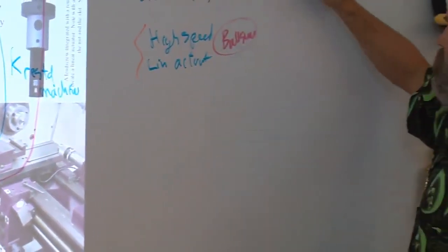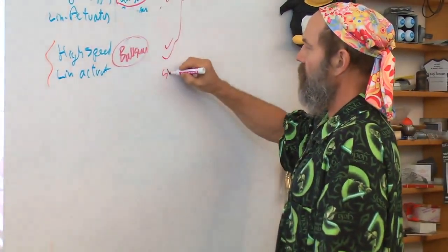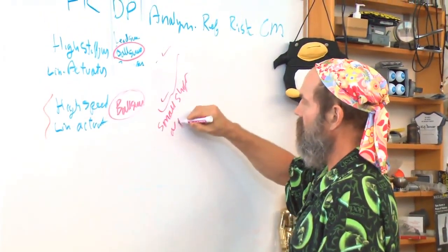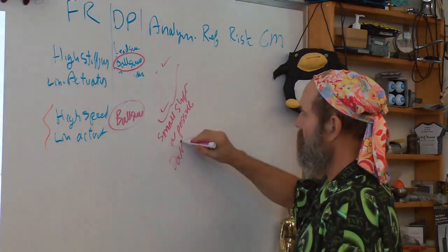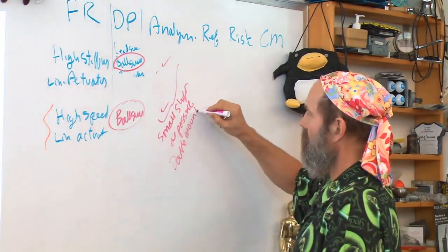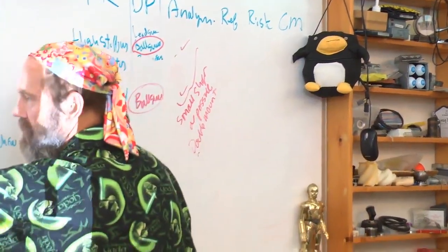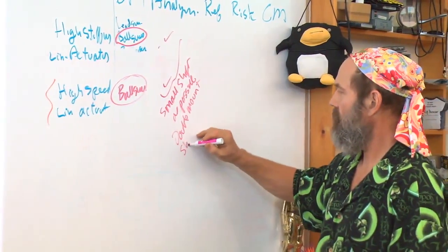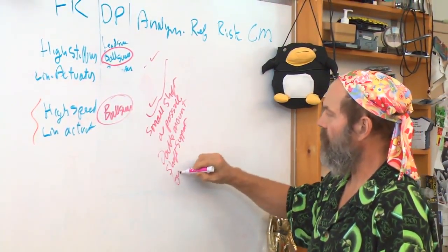And we did our analysis, so we check, and this told us use as small a shaft as possible and double mount the shaft. So we have mount, both ends, shaft support for thrust.